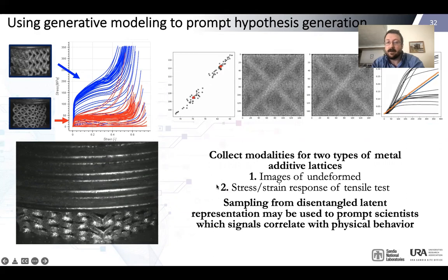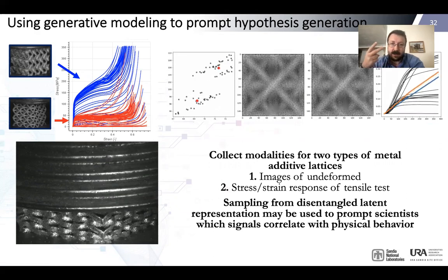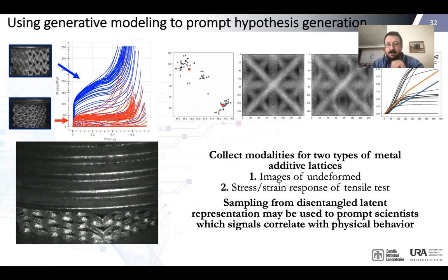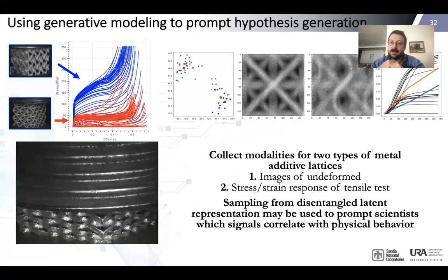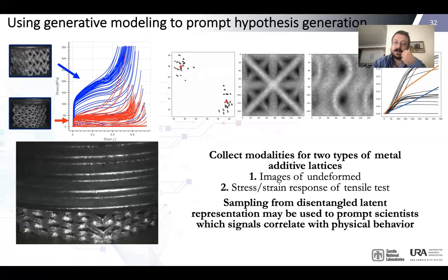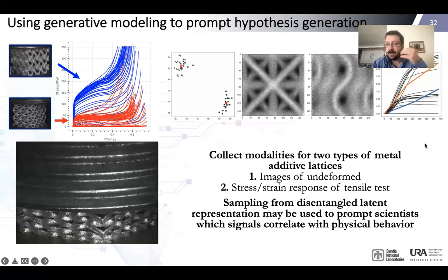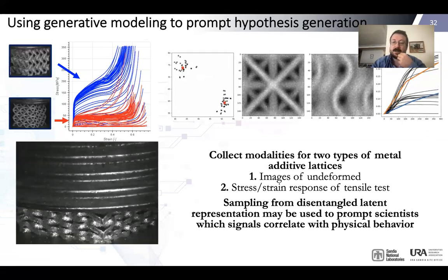And so when you run this algorithm on the left, you can see each black dot corresponds to a pair of these two modalities. The red dots are clusters, and you can see it's swapping these black dots back and forth until it's figured out the two subpopulations in the data. And then what it's doing, all the way on the right, is using this physics model to fit a linear strain hardening model to the data, right? So you're asking for these two subpopulations so that you get it in terms of the mechanics of the problem.